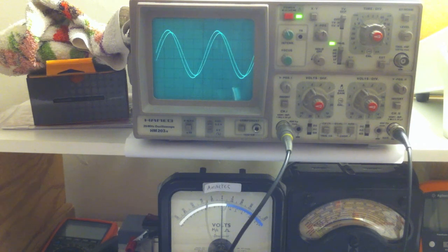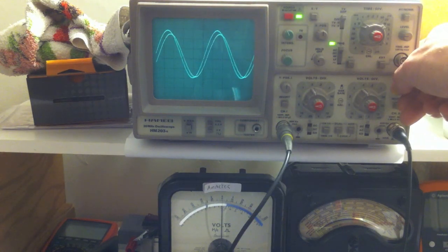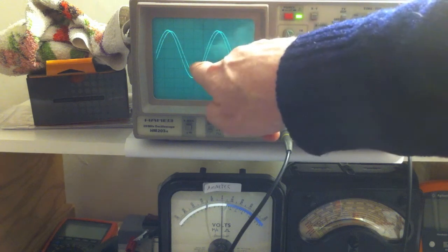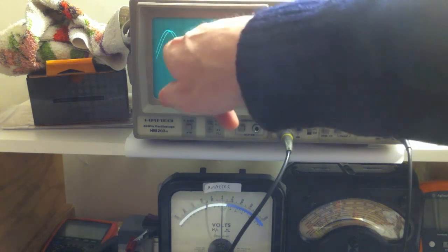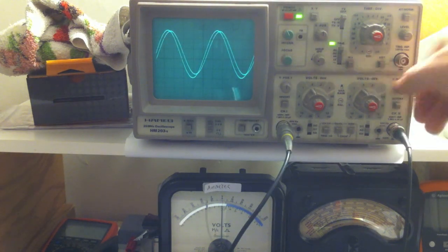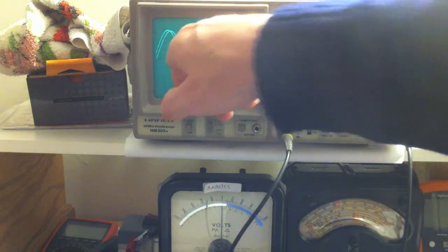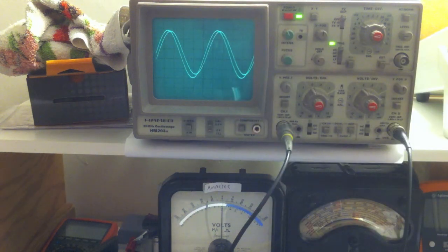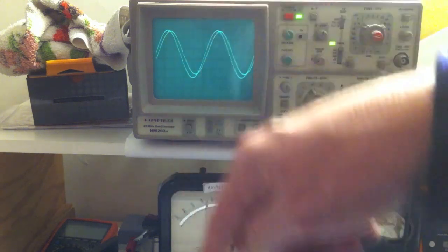And that's why you get the carriers, the charges, going between the voltage in and the capacitor. So during this upswing here, you can see that the capacitor voltage is above in value the input voltage. Because the capacitor voltage is slightly higher in this part of the curve than the voltage in, then obviously charges are going to go from the capacitor back into the V in, because the sine curve now is going in the opposite direction.